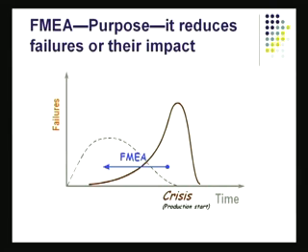If you do not do FMEA, then the design or the process would be released as is without any kind of prediction of the chance that it might fail. It may fail to function as required, or it may fail to deliver the performance that is expected of it. That is something that would be there if we do not do FMEA. So FMEA is a preventive, predictive technique. That's what it does. And it leads to actions that will lead to improvement in performance.